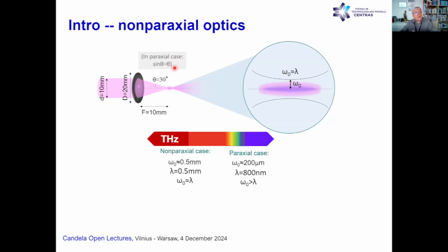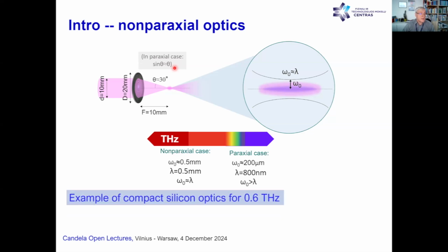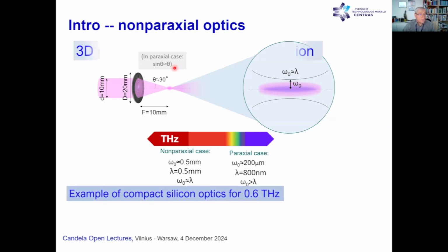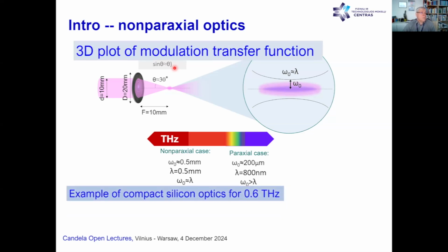And we try to consider a compact imaging system placed on a chip. Our way is not conventional optics. Our way will be non-paraxial optics with the Sommerfeld-Rayleigh integral behind it. What we need to use is not simple optics formulas available from the textbook, but a numerical solution of this integral. With the exact, complex solution, we can see what can happen in imaging terms.